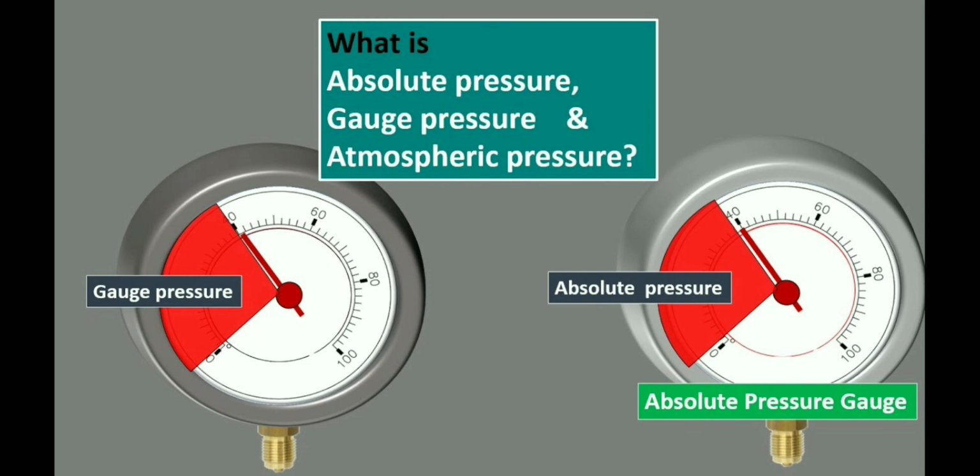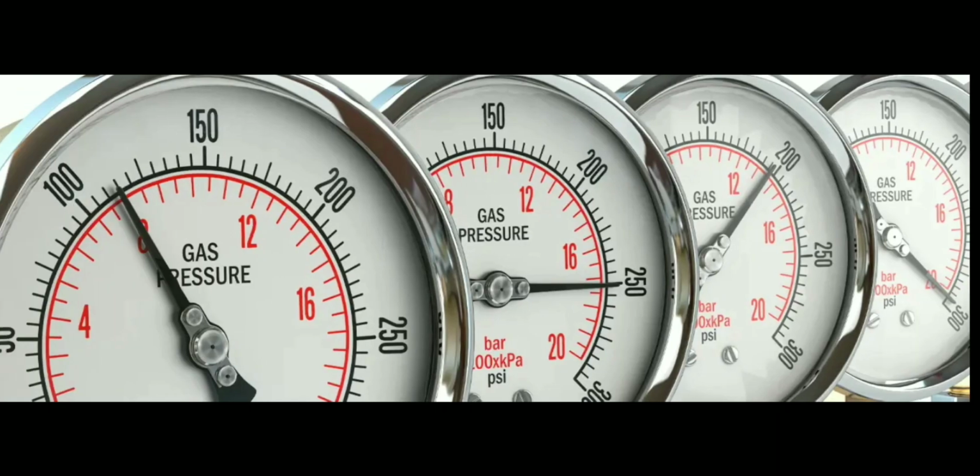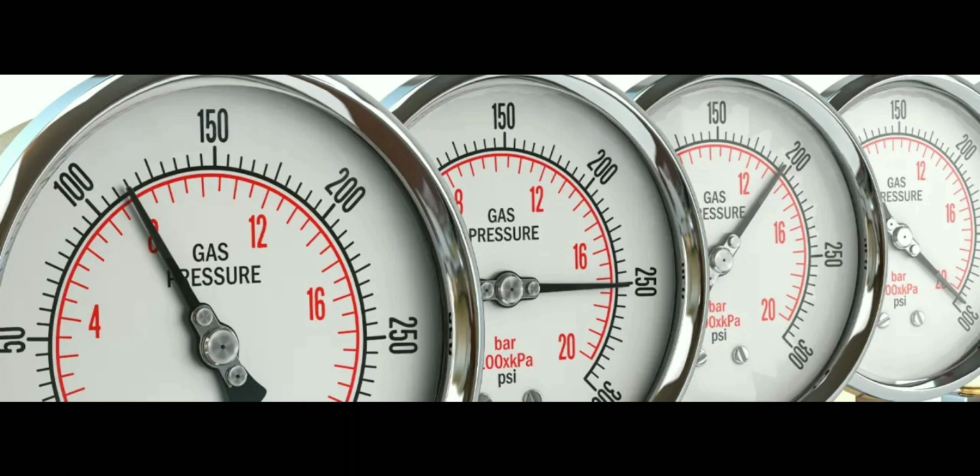An absolute pressure transmitter is suitable for installation at various elevations as it measures the pressure relative to a vacuum. In a gauge pressure transmitter, installation at a different elevation affects the reading, as the atmospheric pressure varies with altitude. Absolute pressure transmitters are used in vacuum systems, barometric pressure measurements and altimeters. Gauge pressure transmitters are used in industrial processes to monitor pressure in pipes, vessels and equipment.